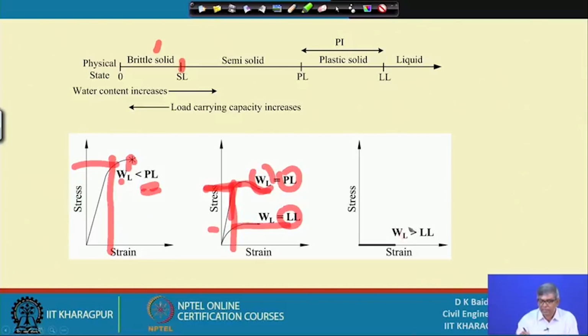Similarly, if the water content is equal to the liquid limit, then it is like a liquid, and if I apply force it will not be able to take any force. Because of that you can see there is no stress here, that means without any increase in stress the straining will be very high. So it will not be able to take any load.